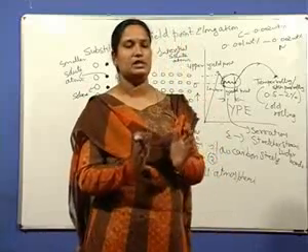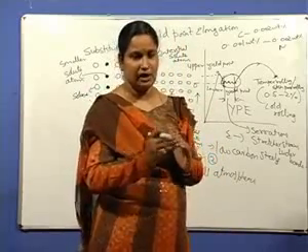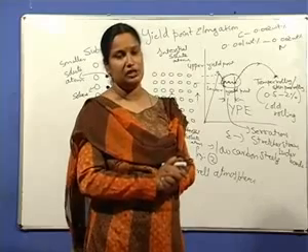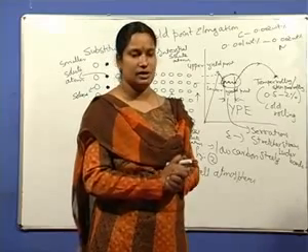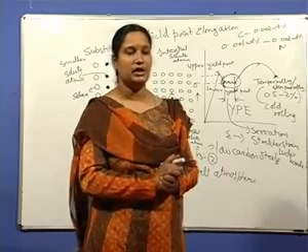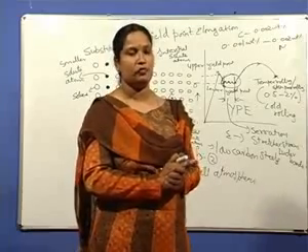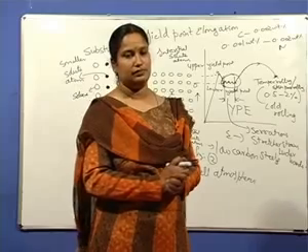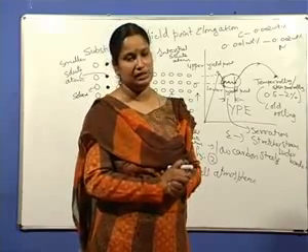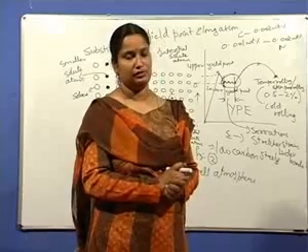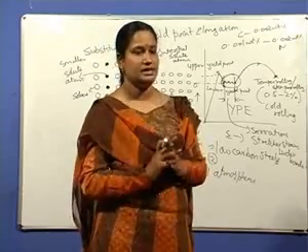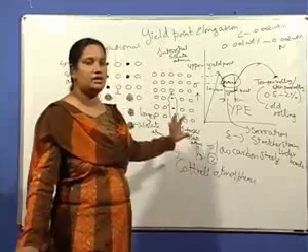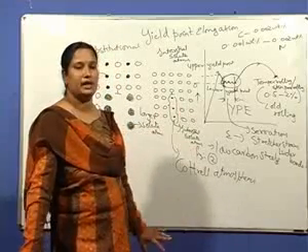That means the reappearance of the yield point phenomenon occurs at a slightly higher stress because of room temperature aging. This is known as strain aging. The reappearance of the yield point at slightly higher stress, due to room temperature aging, is known as strain aging. So in order to clearly understand, I draw one more figure for this strain aging. I hope at least you have understood the reasons for yield point elongation till now.